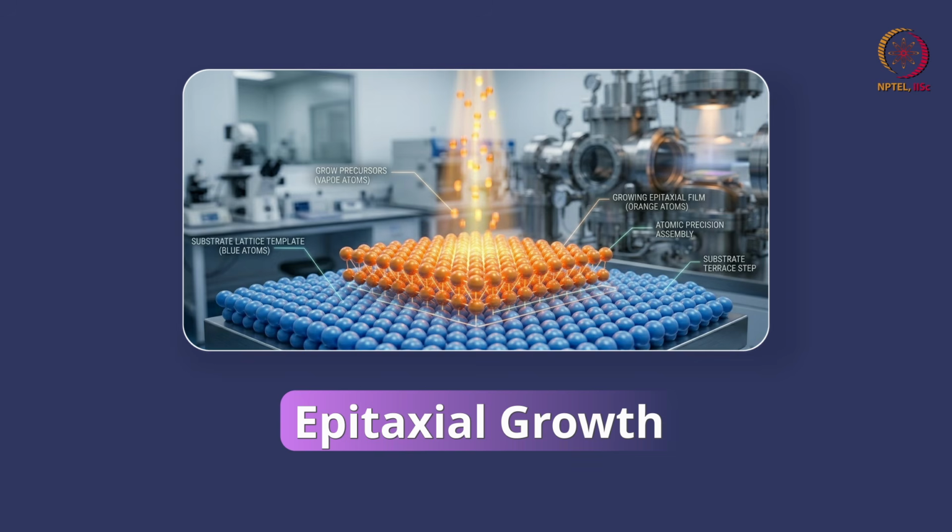There are classes of materials which are just single crystalline materials grown atomic layer by atomic layer in what is called an epitaxial growth. Now, there is a huge amount of elasticity, that is the strain that comes from the substrate or the stresses in the film themselves, that play a role in how these materials grow. They are going to add on to the G's, to the free energies that you have calculated using bulk thermodynamics. So that will influence how your material is growing, what is going to be the shape of this material, what is going to be the mode of growth of this material, and so on and so forth.